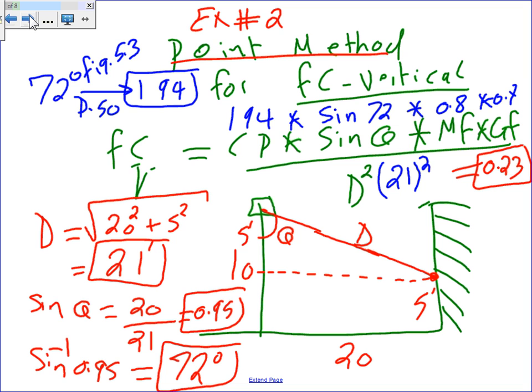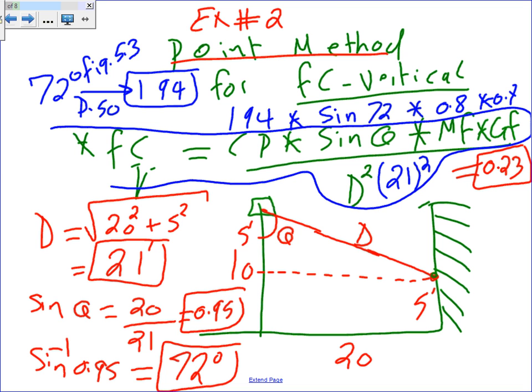The distance squared. No cubes, unlike I told you, no cubes here, nothing. Just the distance squared. Okay, take this fixture. Here's the same fixture that we have, guys, 20 feet away. And I need to find the foot candle right at this point. One more time, we know that the formula for the foot candle on a vertical surface is this one: the sine divided by the square of the distance, with a bunch of other factors.